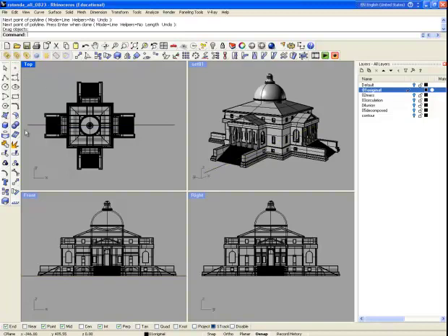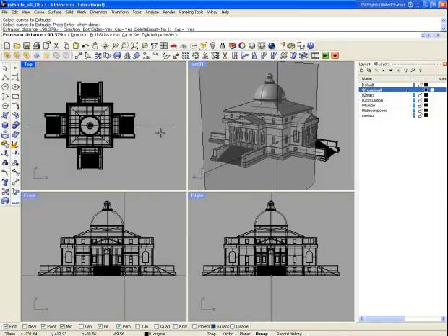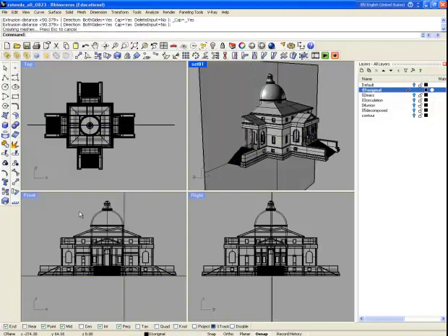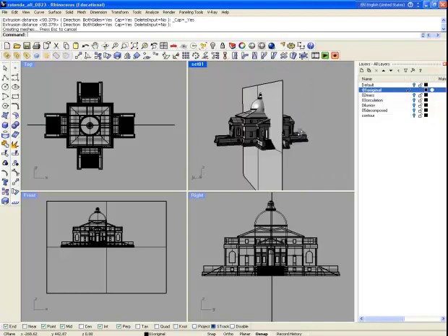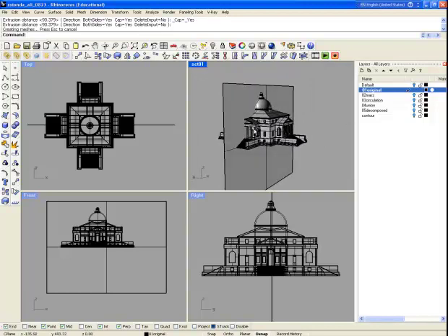And then we are going to extrude that curve by clicking this one, right click, and then you're going to see this command which is called extrude closed planar curve. Click it and then select curves to extrude. This is the one, and enter. You can just right click, which means enter. Are you going to extrude both sides or one side? For now we are going to use both sides. So as you see, it's yes. That's why my extrusion is made on both sides. Over here I think it looks long enough. Click, and so I have a section cutting surface as you see on the screen.